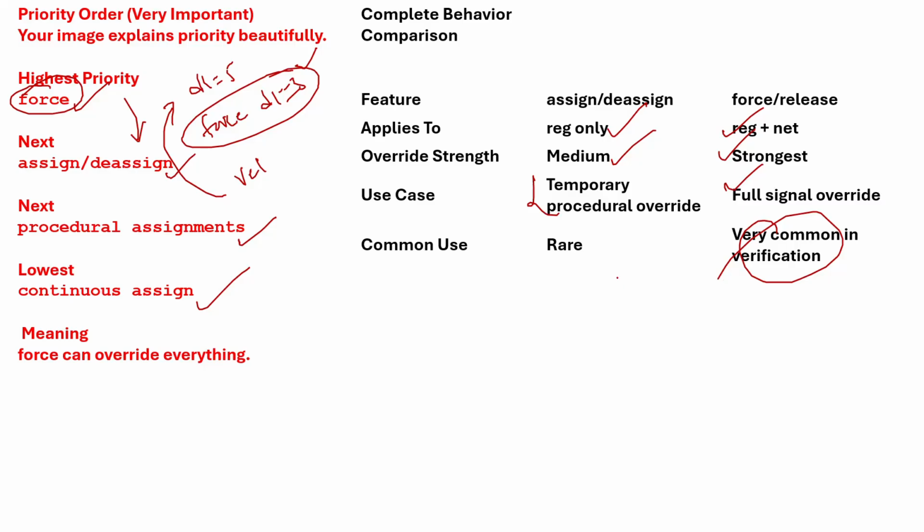Assign and deassign conditions are not utilized because if you utilize assign and deassign you may get confused, since you are utilizing the data flow model or other types. Because you are applying register assignments, that register is utilized in procedural assignments only. That is for sequential circuits only, right?